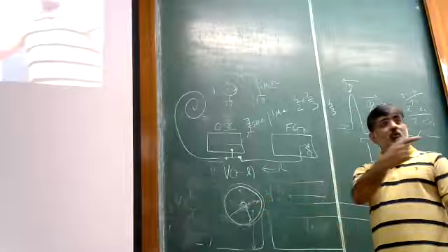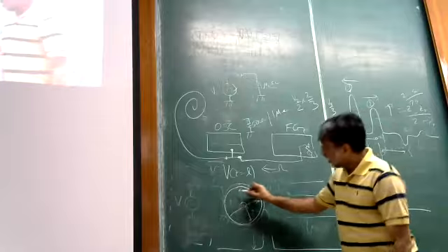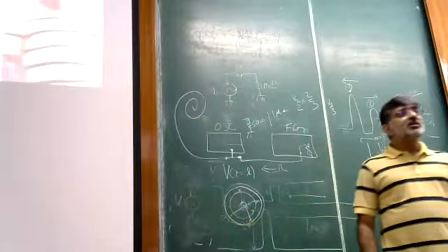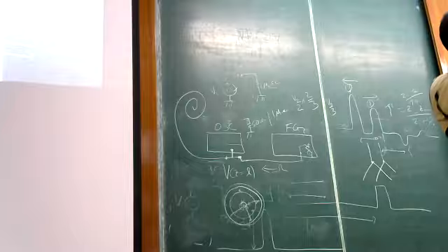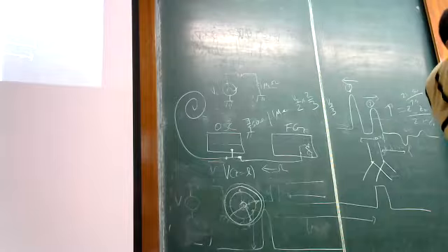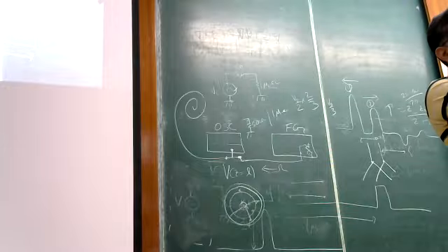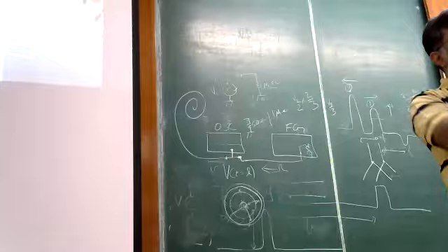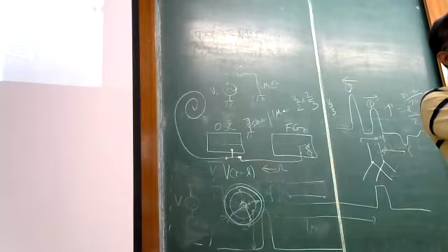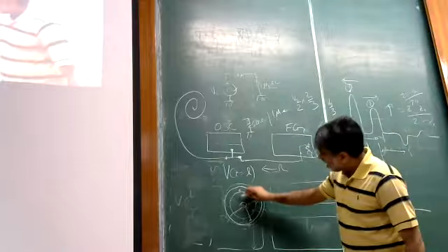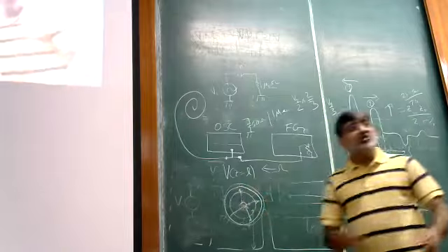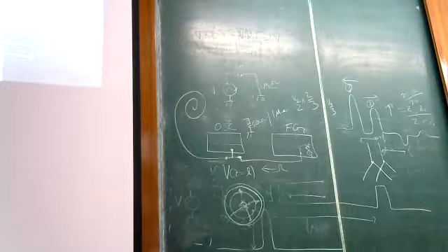And because currents are flowing through the center conductor, magnetic fields are going around in circles. So if you now imagine this is the center conductor and the current is flowing, for a parallel straight line carrying current, you will have magnetic fields which are like this. Okay. So magnetic fields are going in this circular fashion in a plane which is perpendicular to the direction of the transmission line, and electric fields are going radially outwards. So if you notice, that means that the direction of the electric field and the direction of the magnetic field is always perpendicular to each other.